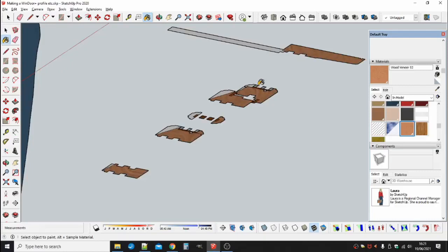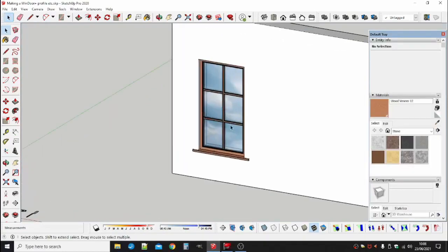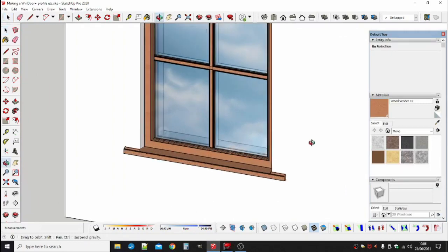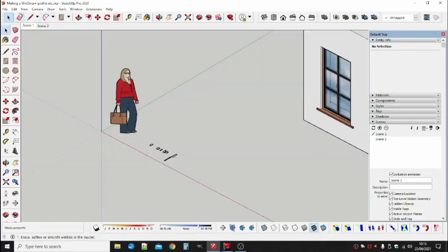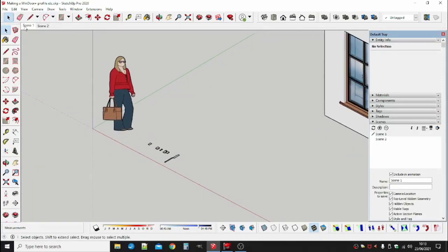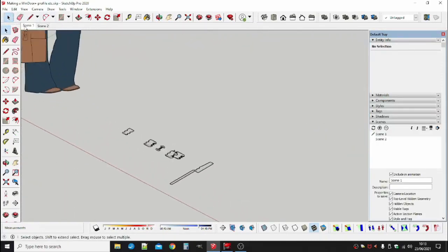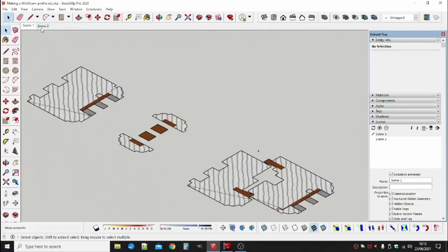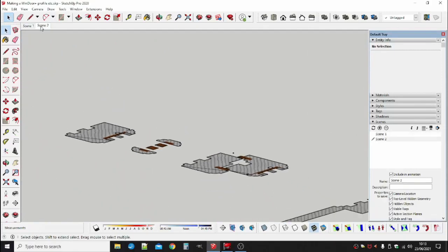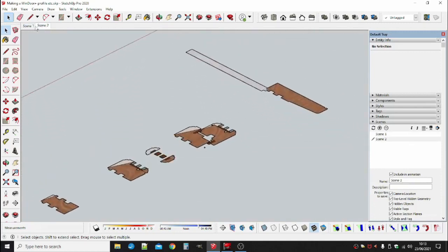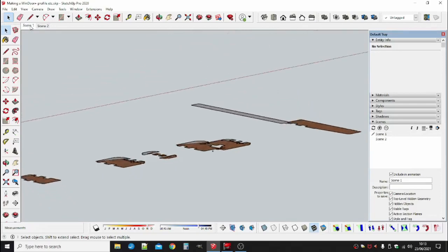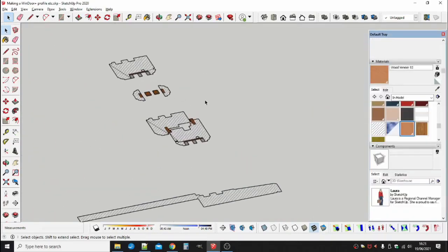The front face is painted white on the part which will show inside, and timber texture on the part that will show outside. When installed in a wall, the window will appear timber from outside the building and white from inside the building. I have coloured both faces of the draft strips and glazing glue a dark brown colour, but you can paint any of the faces in the components, front or back, with any texture you want. It's up to you. I've chosen these textures to show you how, and because they are common enough finishes for a window and for window profiles.